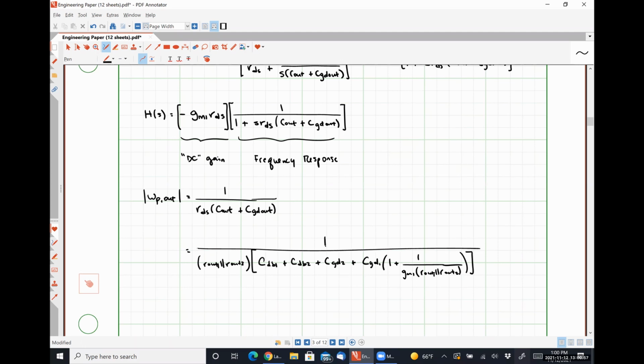All right, so we have a single pole system, and the capacitance that was referred to the input doesn't affect our frequency response at all, right? Everything that we have here is the crap that's been thrown to the output side, okay? That's going to be very important because when we analyze our op amp, it's going to make things much, much easier because we don't have to look at any contributions from our input nodes. Okay. So any questions on this?